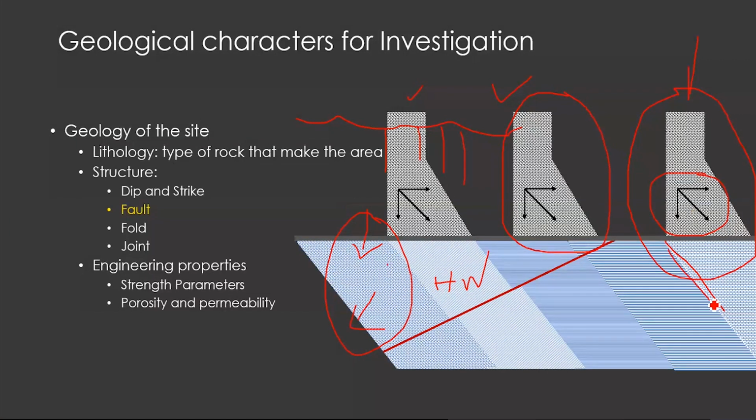The bedding plane is running, or the effective load or force is going to be applied parallel to the bedding plane, and that may give rise to some movement along that, or the weakness along that. But if you consider these other two things, where the forces are running perpendicular to the fault plane, the forces acting on this may be a little more suitable. So this is how the reasoning is to be done. That is what I'm discussing here. Rather, these are not ideal conditions that we expect in the field.